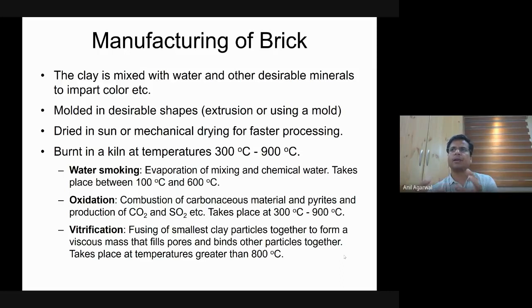So there may be water available as chemically bonded water in the minerals, and there may be free water available. Free water will evaporate very quickly at around 100 degrees centigrade, but chemically bonded water may take up to 600 degrees centigrade to evaporate, because for that the chemical bond has to be broken. Okay, you may remember from your chemistry classes that water sometimes bonds with minerals chemically.